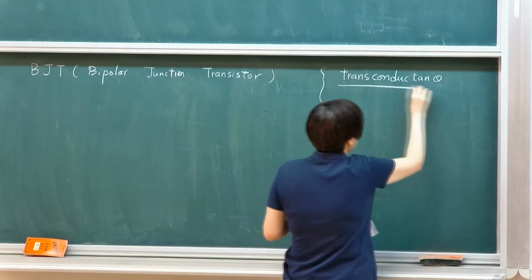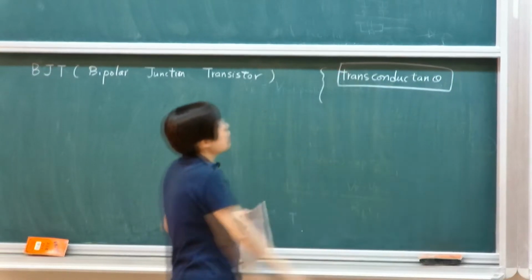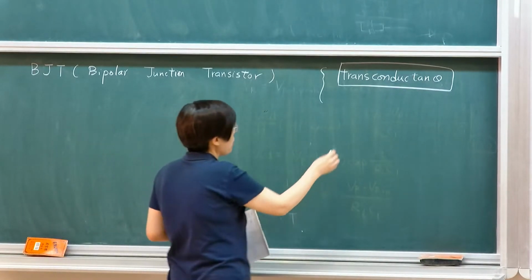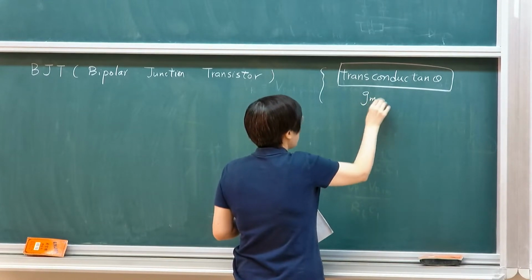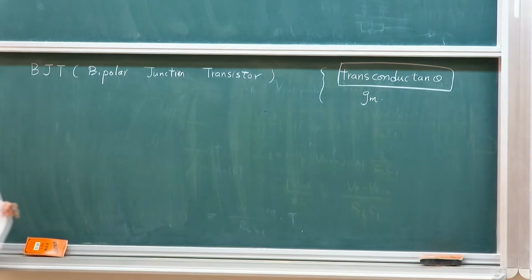This is one of the key performance factors called gm, which is transconductance. The idea is that through the third terminal, you want to control the current between the other two. For a diode, because it's a two-terminal device, you're unable to provide such a structure. Transconductance means you have a third terminal which controls the amount of current flow.